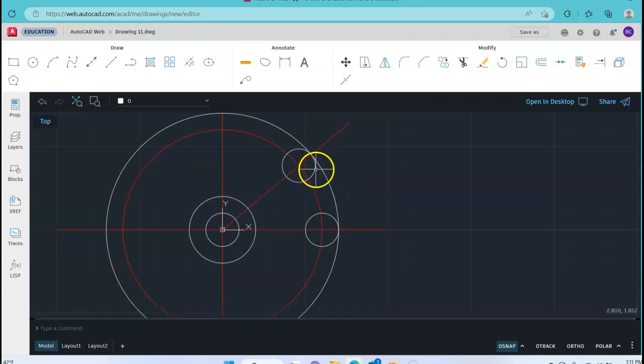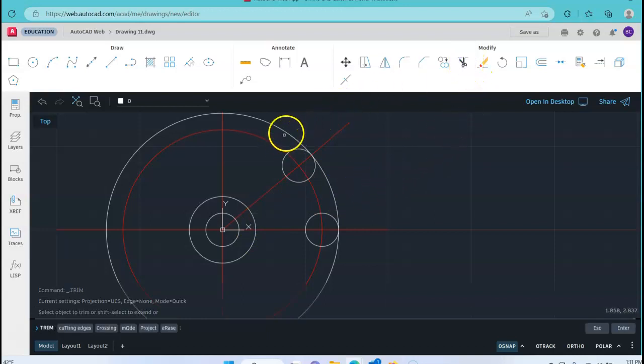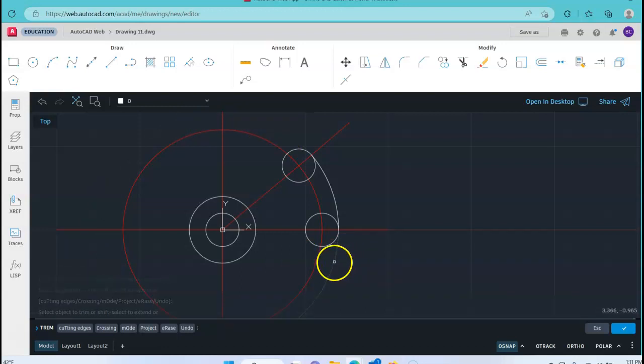Now it's where I want it to be. I think before when we did it, our cursor was over here, so watch your cursor to make sure that it's where you need to be placing it. Again, now I can come up to my trim tool, and I'm going to trim and get rid of all of this. Notice how it's making me do this in quadrants because our center lines are kind of keeping that and kind of trimming the lines to those other lines.